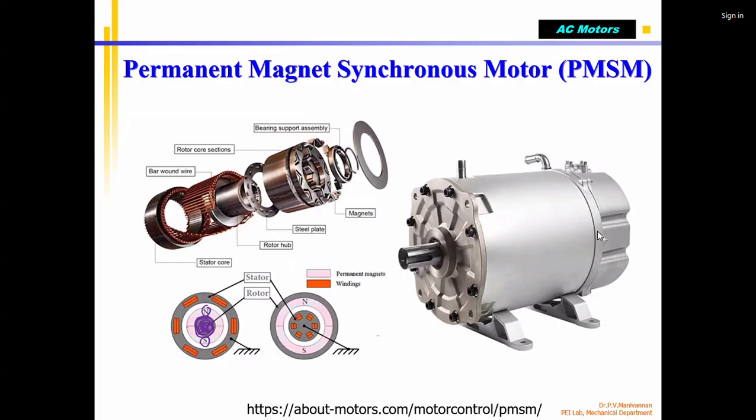So this is your rotor. This is called surface. On the surface of the rotor, the magnets are mounted. That's why you get a surface mounted permanent magnet rotor. The other one is interior, IPM, interior permanent magnet. So you can see that these are the magnets. Correct? So the magnetic poles are inside. Okay, I will show you the next slide so you will understand what it is.